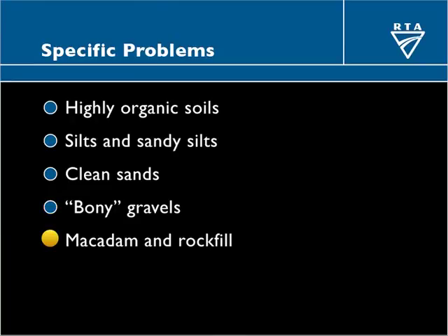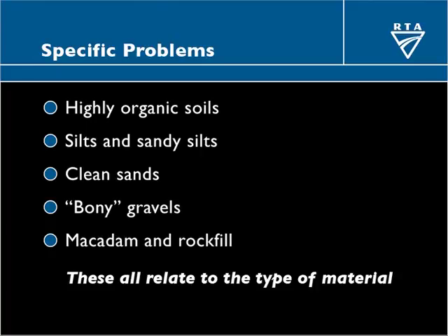And finally, macadams and rockfills are in a class of their own. You can't laboratory test them the way we've been discussing for soils, and you have to work them out in the field. Often you have to have a very specific attempt to develop an appropriate compaction routine. Again, we'll discuss that a bit later. Now, all of those issues relate to the specific type of material and will only be found in those types, not in general materials.